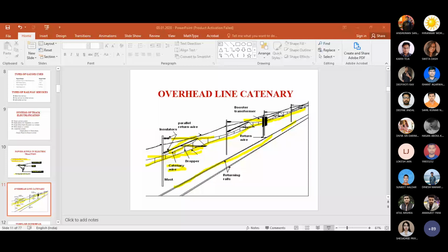That neutral wire is grounded at your pole-mounted substation. What is a pole-mounted substation? In your locality, you can see a transformer that is installed near your homes. That transformer may be assigned to maybe 50 or 100 homes in your area. The neutral is grounded.